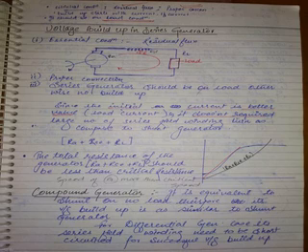You require a constant voltage across any load, across a fan, across a bulb or any load. If the voltage is varying, automatically the bulb fluctuates, the fan speed will fluctuate. Like that, you require a constant voltage across any load. But what is happening to the series generator terminal voltage? It is rising in nature. It's a variable voltage. That's why it is not at all useful for normal power supplies. It has specific applications. Later we'll discuss the characteristics. But here, write down some points.